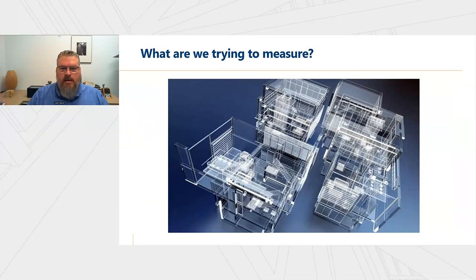All right. Simple question that needs to be asked throughout the design process, and certainly before the testing is done, is what are we trying to measure in terms of, what is the envelope or the enclosure that we're measuring? What is the extent of the air barrier? And, if you're thinking about a simple case and you've got a rectangular prism for a building, it's probably just all 6 sides.